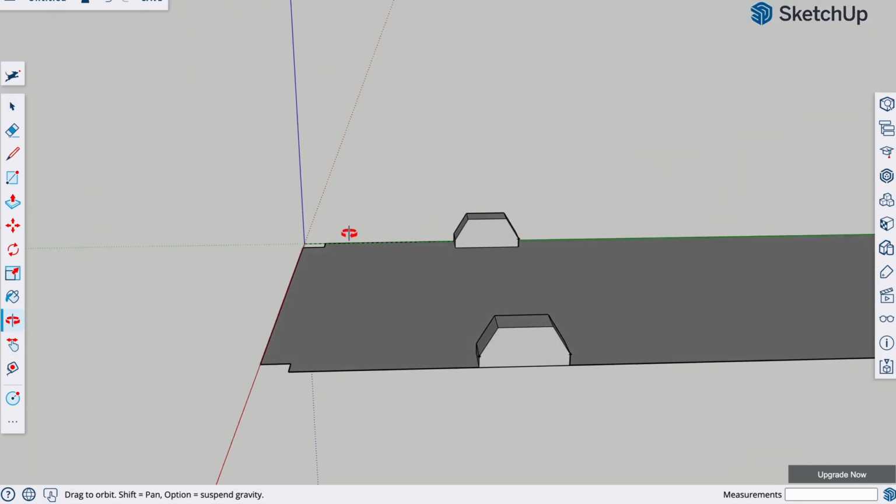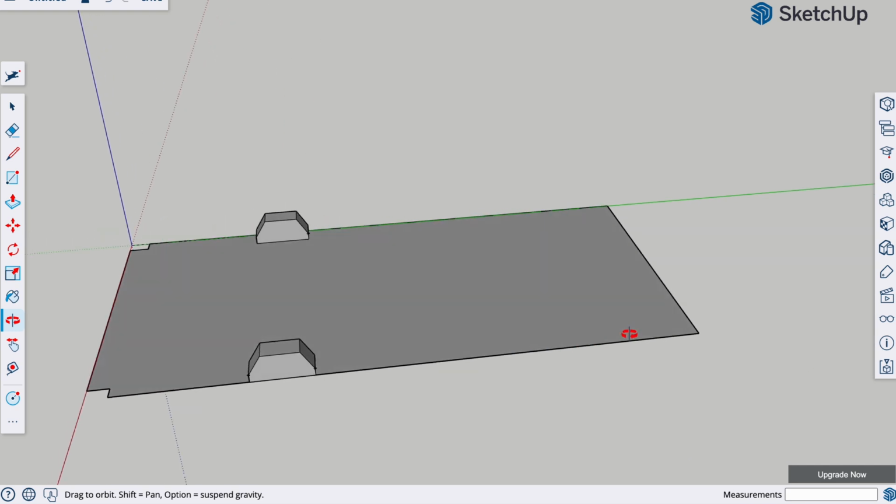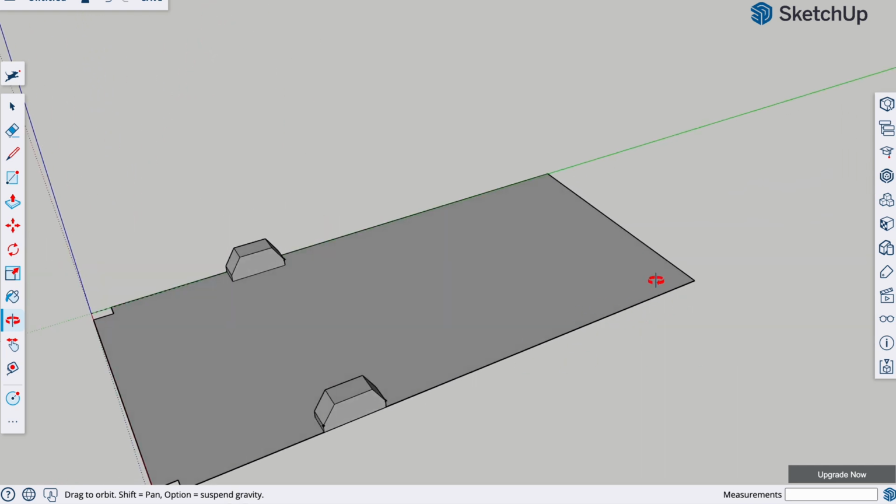All right, excellent. So you have your wheel wells. The next thing I would do is start to draw out your slider step. Most people have a slider step. Let's hit the tape measure. Maybe it's 6 inches in, and it's usually 3 or 4 feet long. So let's do 36 inches from there and say it's 7 inches deep. We'll connect those two and do 36 inches by 7 inches deep. Now we're going to single click that area, hit delete, and hit that small line, hit delete. Perfect.